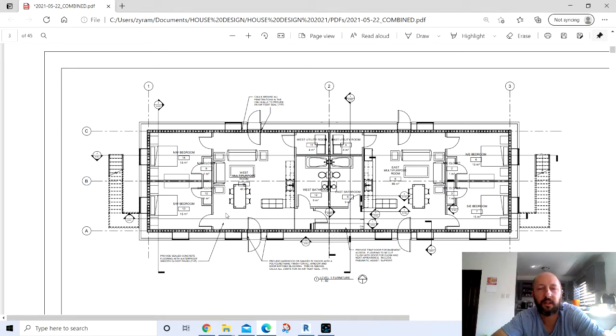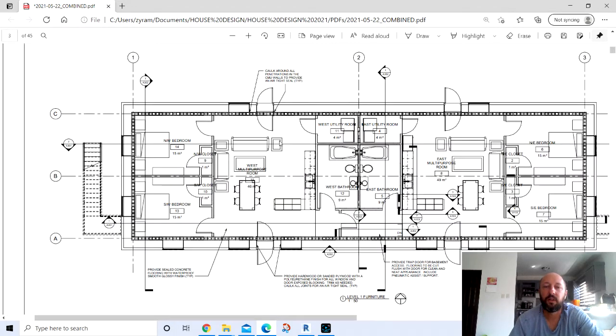And every different type of mass, whether it be water or concrete or air or plastic or whatever it is, has a different energy density. The energy density is how much energy that object can store, and concrete has a high thermal mass. Water has one of the highest ones, but I didn't really want to make the floor out of water, so we went with concrete, and also it's pretty structurally sound. So a concrete floor, 4-inch slab on grade on both sides.